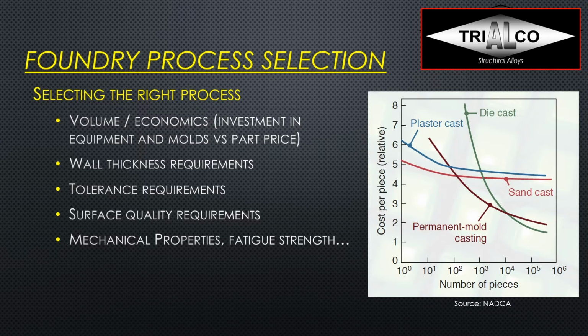They all depend primarily on the freezing rate of the aluminum alloy, and therefore on the process, because, for example, in die casting, you have a very high freezing rate. The metal comes into contact with a cooled steel mold, so it freezes very quickly, especially if it's thin-walled, versus in a plaster cast, where the molds are made of plaster, or sand cast, where molds are made of sand, and then it contracts away, so you have an air barrier between the mold and the solidifying casting.